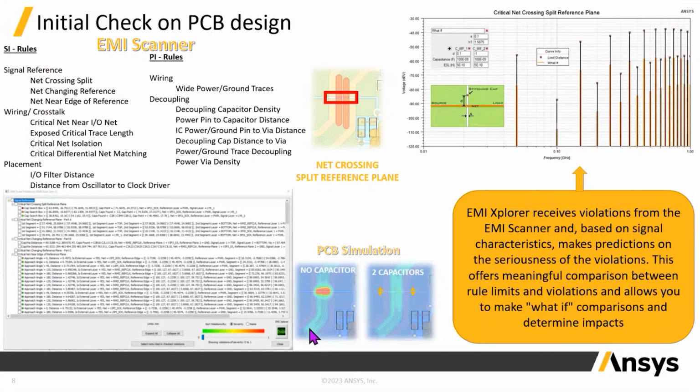So you can see there is a PCB net which is passing through, and the grounds are split over here. Because the ground is split, or there is a gap in the ground, a high electric field is formed. This can lead to emission in the EMI/EMC sense. To avoid this, you need to add a stitching capacitor. You can see that by adding the stitching capacitor, this high electric field formation is completely reduced. Now you can use it with a split ground.